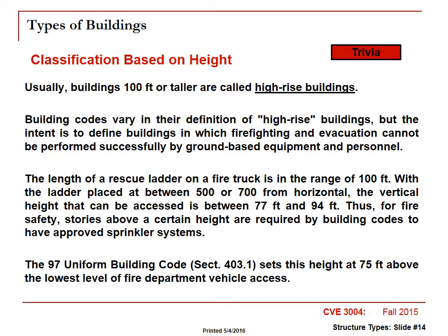When you think about fire safety, and the reach of a ladder on a typical fire truck, generally speaking, the typical ladder can probably reach a point on a building close to about 100 feet. And therefore, this will affect building codes and fire suppression systems that codes require and so on and so forth.